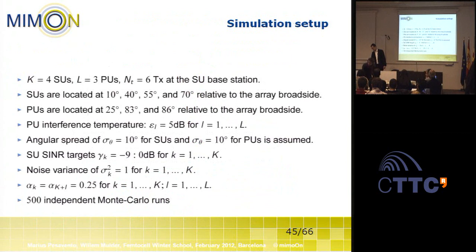In our setup we used, for example, 6 transmit antennas, and we have considered local scattering around the receivers, and that is the separation that we have simulated. Of course, as you have more antennas, this gives you more design freedom to design narrow main beams and deep nulls.